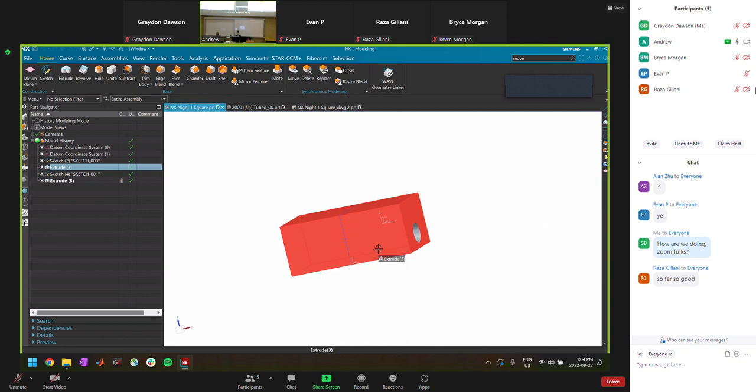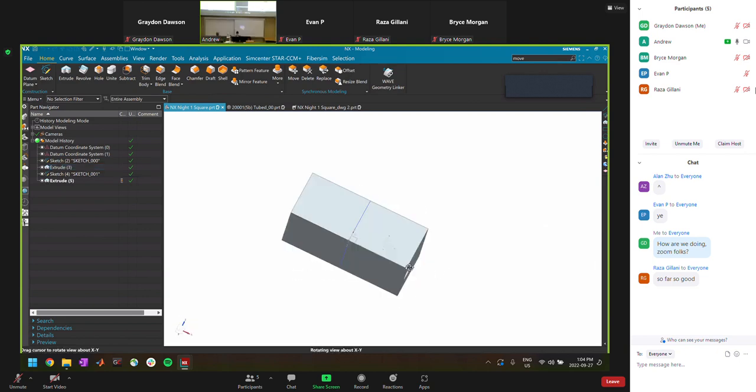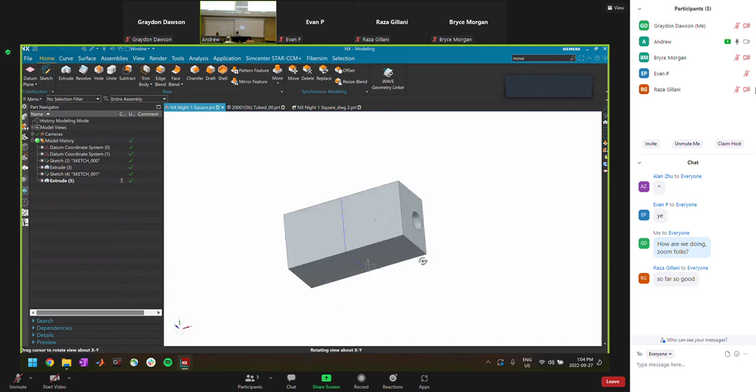That's the rotation center for your part. I think by default it's usually the global coordinate system origin, or sometimes it assumes center of mass. But sometimes when we're doing funky things, we want to select a specific point for our rotation center to be.